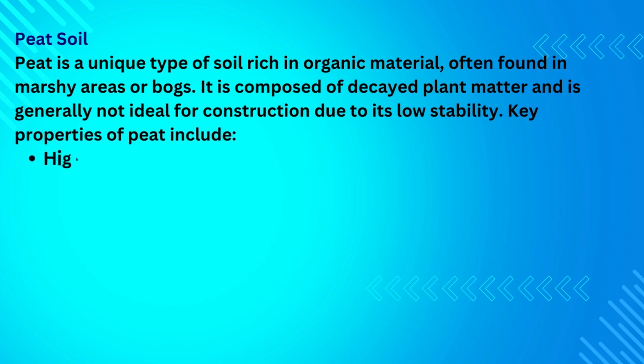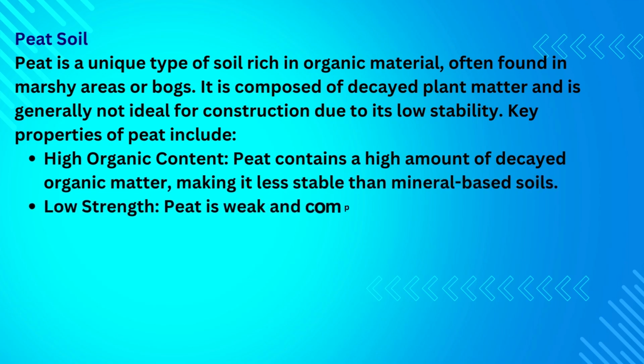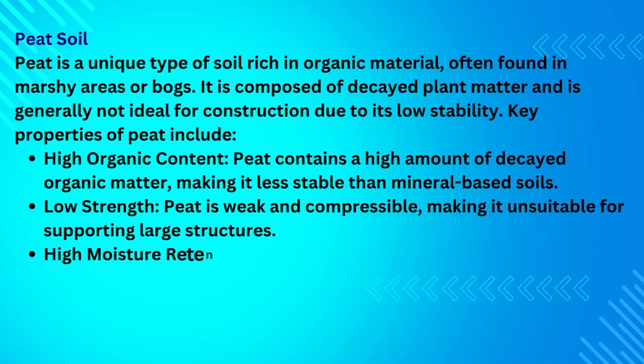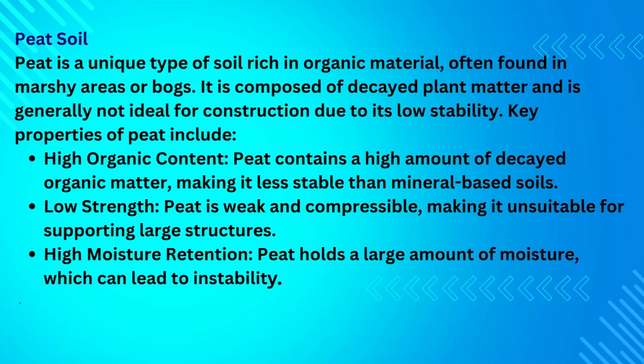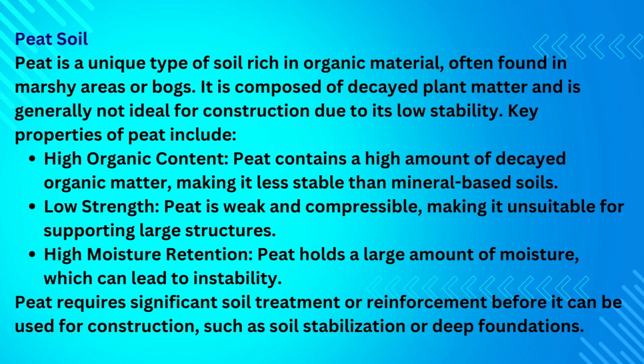Key properties of peat include: high organic content. Peat contains a high amount of decayed organic matter, making it less stable than mineral-based soils. Low strength. Peat is weak and compressible, making it unsuitable for supporting large structures. High moisture retention. Peat holds a large amount of moisture, which can lead to instability. Peat requires significant soil treatment or reinforcement before it can be used for construction, such as soil stabilization or deep foundations.